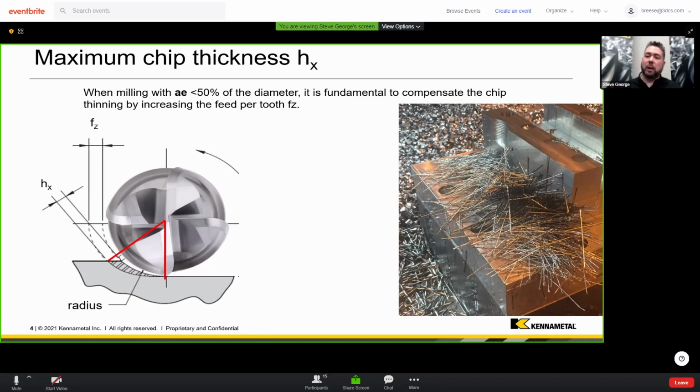A lot of people are going to think of that as slow. I personally don't do slow, okay? My job is to make things go fast. So when I talk about maximizing traditional cuts today, I'm not talking about running an old Bridgeport. I'm really talking about HPC type of stuff: heavy chip load, heavy radial depth of cut, max the spindle out that way, okay?